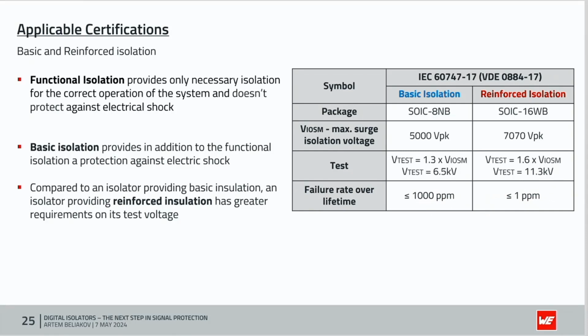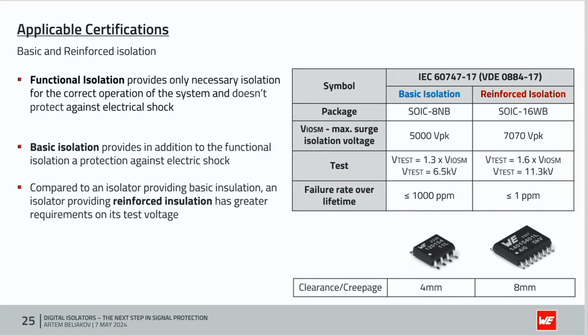VDE standard doesn't specify any requirements for creepage and clearance distance. I mean, it doesn't specify the shortest distance between input and output terminals. But test isolation voltage and clearance and creepage distance have a strong connection, as you can see on this small table.